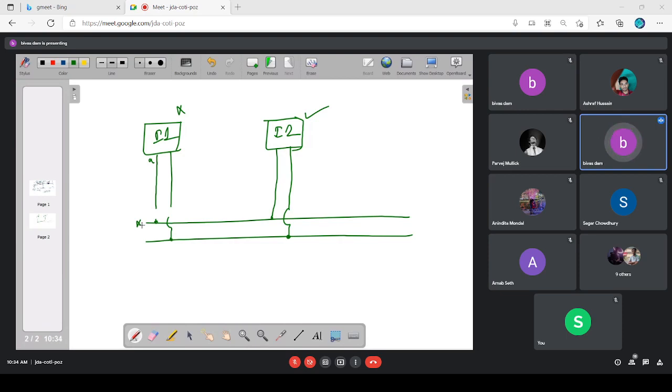What I require is, in case one input device is supposed to be disabled, its output should electrically isolate itself from the individual wires of the data bus. Now, electrical isolation means it must place infinite impedance to the external world. If one node places infinite impedance to the external world, then I can say that this particular node is electrically isolated from the external world.